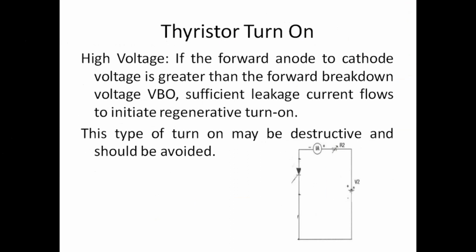Then we need to find out whether there are any other reasons for SCR turn on. Sometimes in your circuits we have not supplied any gate current, and it is not an LASCR, so we have not passed any light. Even though, sometimes the SCR will turn on without our notice. Those are all unintentional, and they can cause damage to the device, circuits or the entire system. So what are the reasons for such turn on? We need to investigate that.